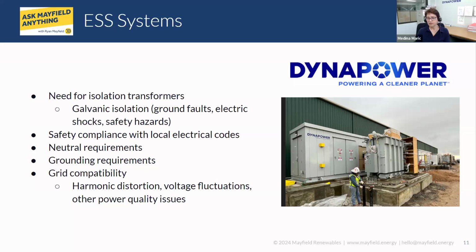The impedance of every transformer is actually acting as a block for any spikes going through. Transformers with lower impedance will have a different inrush current, because impedance helps with inrush current. There are sometimes transformers that are purposely designed to have very high impedance to suppress the inrush and also to suppress the harmonics. The impedance of the transformer will play a big role there.